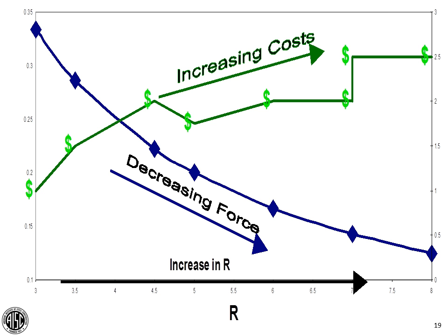Okay. And also, Larry, could you explain a little further when we can provide a contouring fillet to a backer bar versus when we are required to remove the backer bar? So again, the best place to look is to go to AISC 341 and do a search for backing, and it'll tell you exactly when that needs to happen. If you have a pre-qualified connection that you're using, go into that document and look under whatever configuration you've chosen. But generally, the idea is that you can allow the backing to remain and provide the reinforcing fillet if you're to the inside of a section.